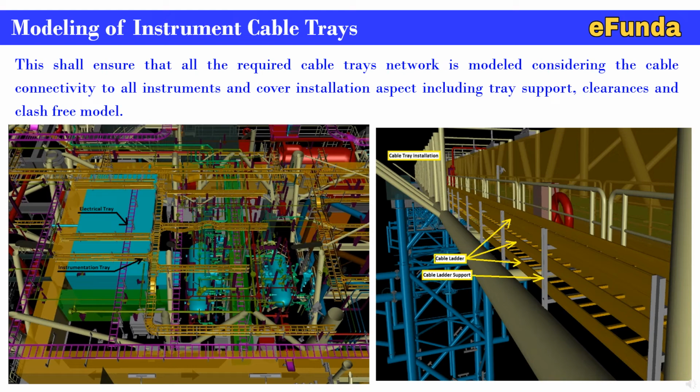One can see how the network is laid across the entire deck area, where intermediate cable trays are also laid so as to have complete connectivity of the trays where you will lay the cable. It will go to each equipment, from instruments to junction boxes and from junction boxes to marshalling. This is how the network is being placed.